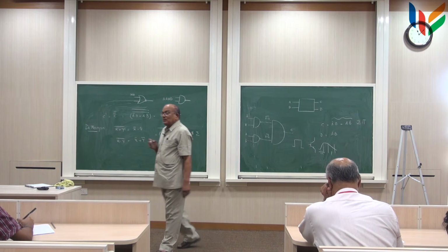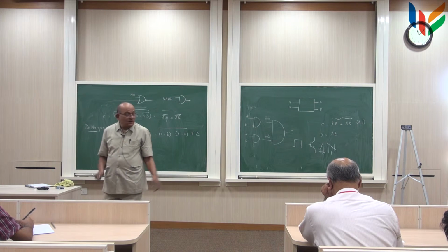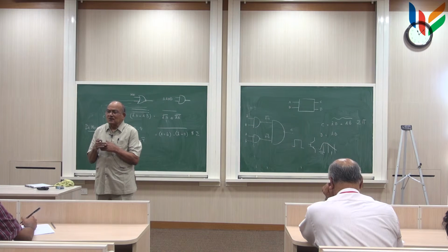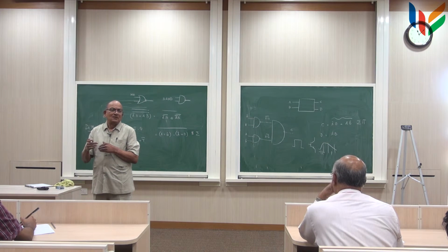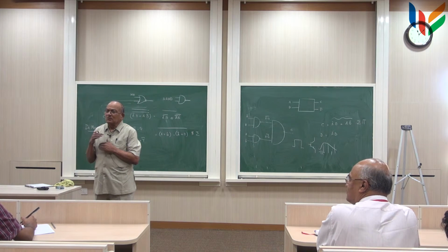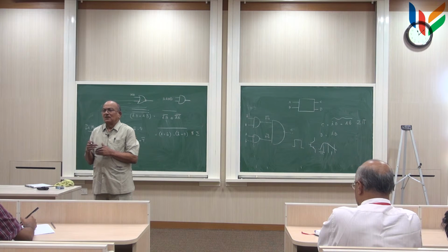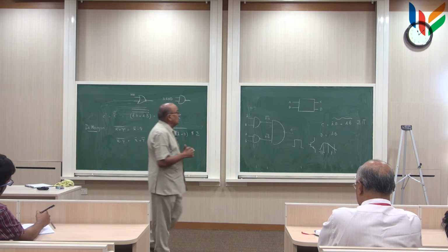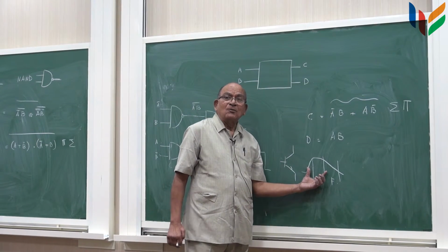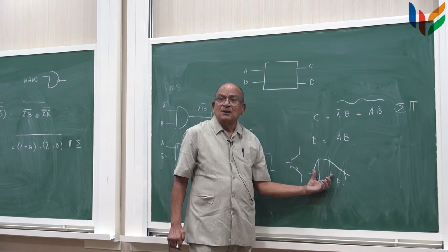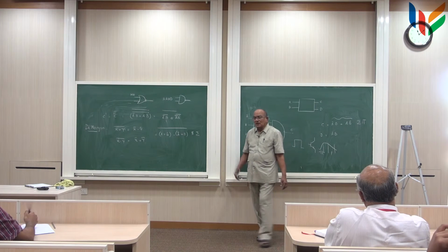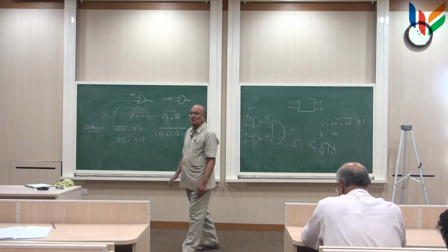And when we were doing the difference amplifier, I mentioned to you that this charge accumulation takes place only because the device gets into the saturation level. In the case of a diff amp, we never allow it to go into the saturated state. As a result, the logic built out of difference amplifiers using BJTs has these times much shorter than any other device, any other topology.